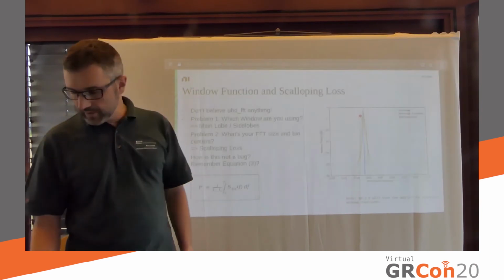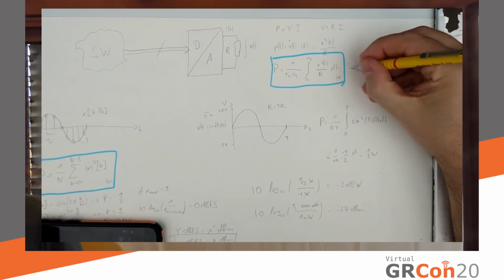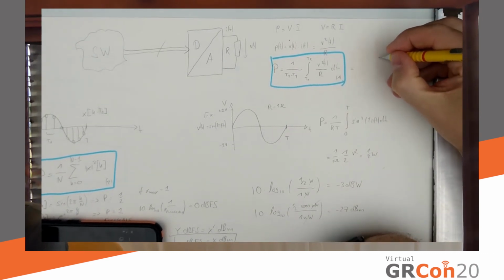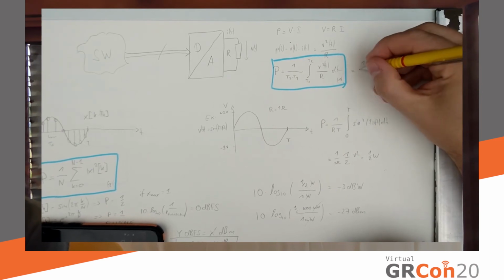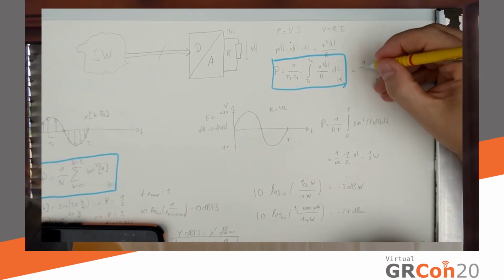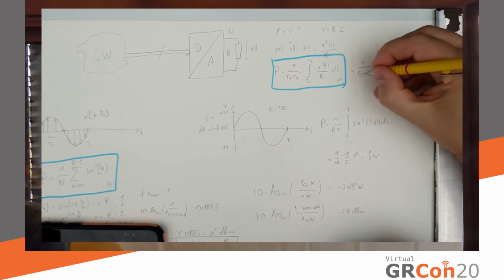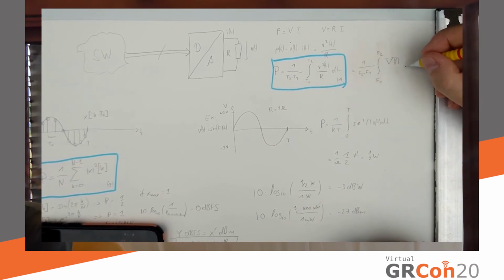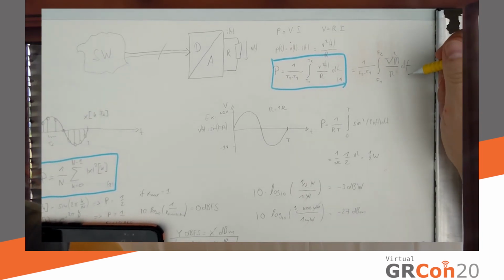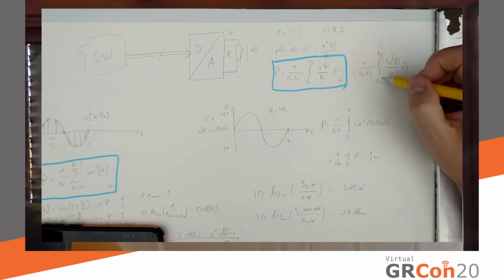Now, there's something very important, and I'm going to go back to my pad for that, which is that you can also calculate power in the frequency domain. That's totally fine. It looks like this. We have two frequencies, F1 and F2, so F2 minus F1. Assume capital V is the Fourier transform of my signal, so the integral of the magnitude of V of f, squared over R, df. This is also a valid way to calculate our power. It's called Parseval's equation. This is only an equality though if my frequency bounds are chosen such that they encompass the entire signal, same as they do with the time bounds.